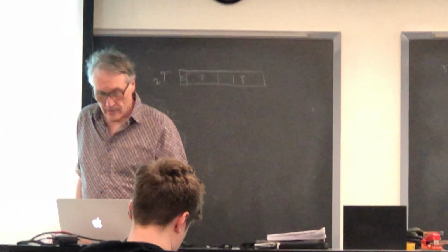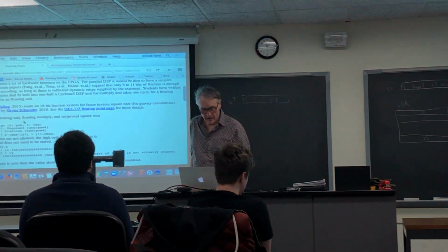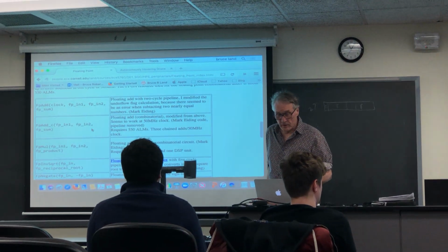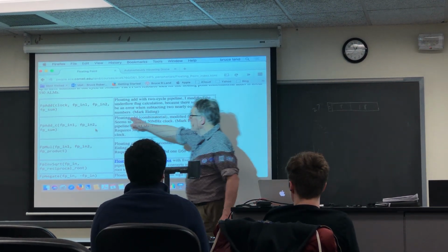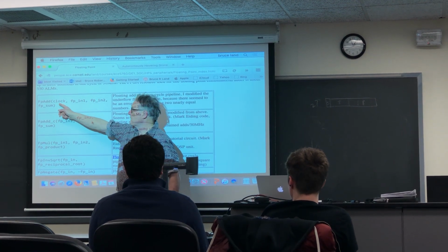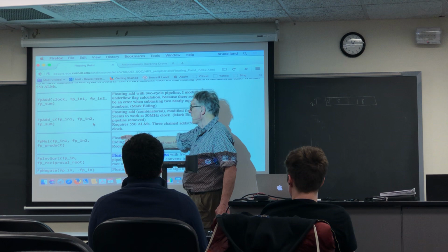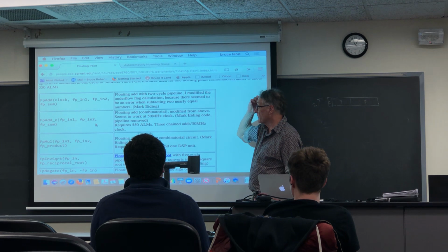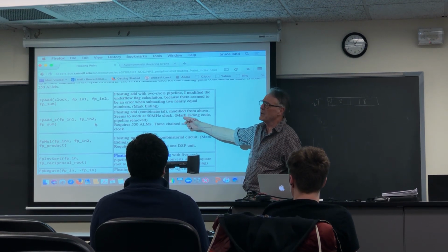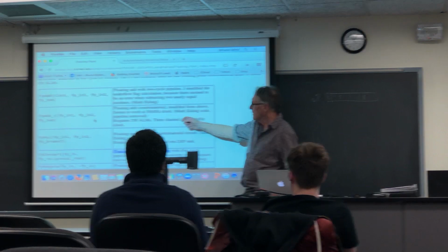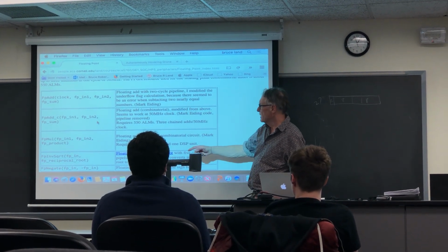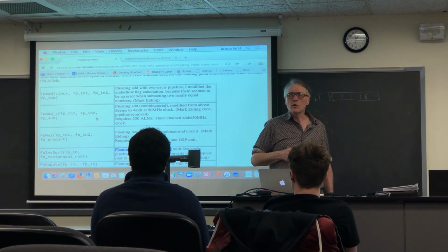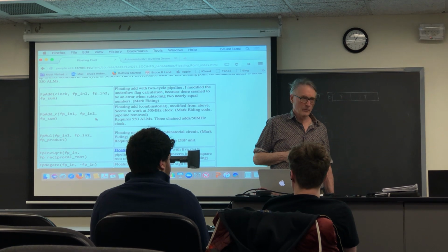And it's pretty fast. Students wrote floating point add. You put in 2 floating point numbers in a clock because it's got a 2-stage pipeline in it for speed. I modified a version to make it combinatorial in case you didn't like the pipeline. It'll work, it'll do an add at 50 megahertz, but maybe at 100 and maybe not. Whereas this will work at below 100 megahertz. Floating point multiply, which takes less work than an add in floating point.